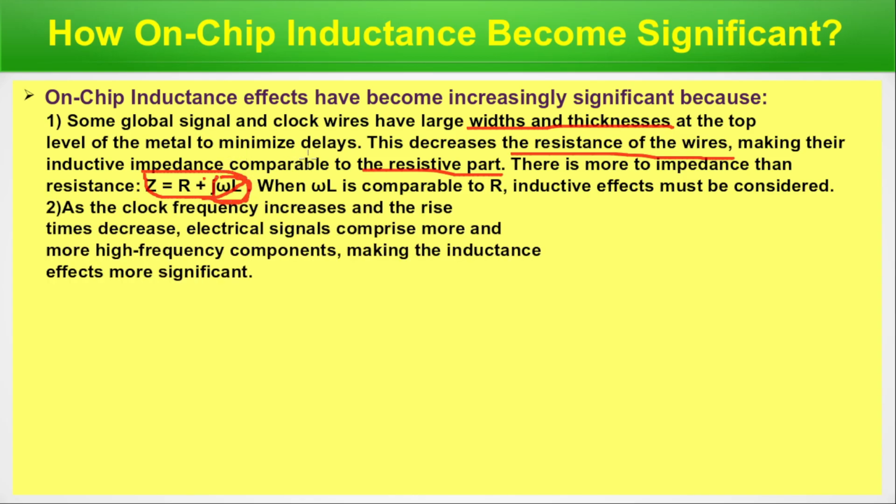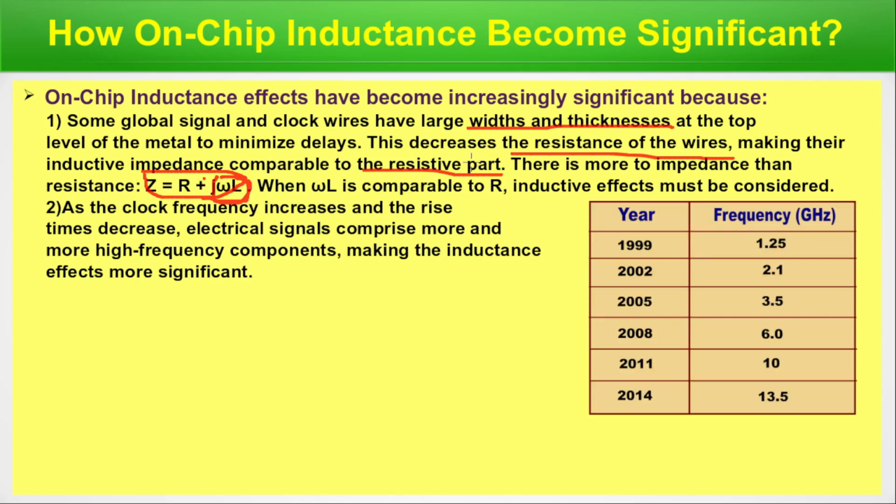Next, as the clock frequency increases and the rise time decreases, electrical signals comprise more and more high frequency components, making the inductance effects more significant. From this first point, the frequency portion is increasing, so the inductance part is increasing, so we cannot ignore inductance effects anymore.